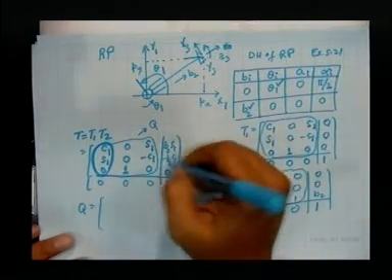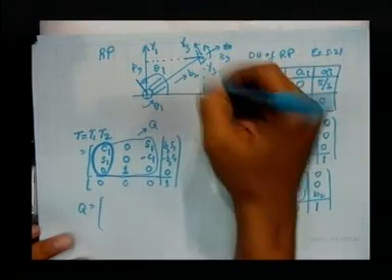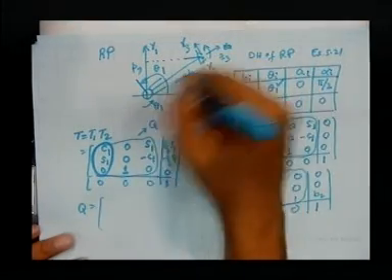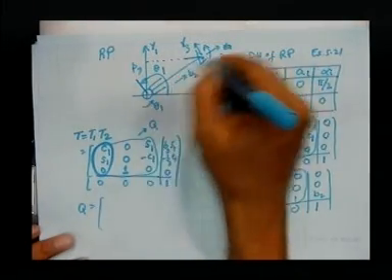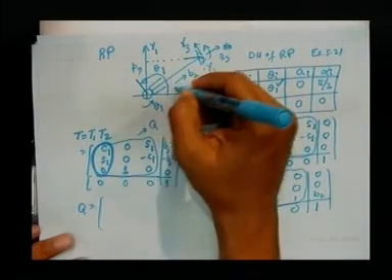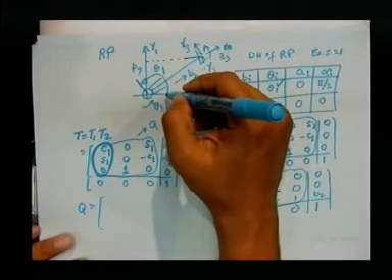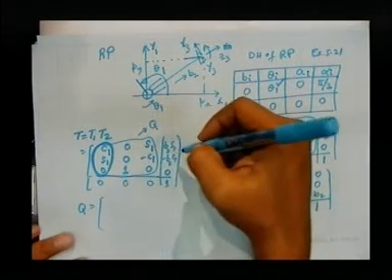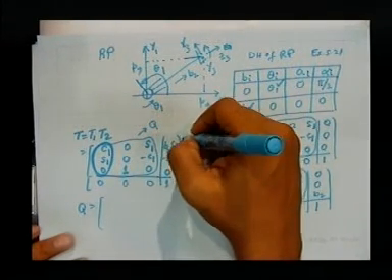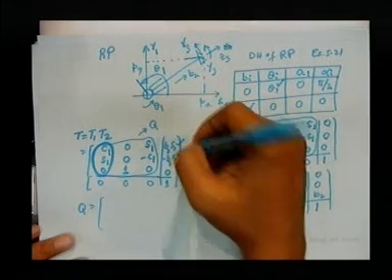Let us look at the simpler one, this portion. This portion means Px, Py. So, what is Px? Px is, this is my B2 here, that means the variable prismatic joint length, right, and then this is my theta 1. So, actually this would turn out to be B2 sin theta 1, and then it will be minus B2 cos 1 and 0.